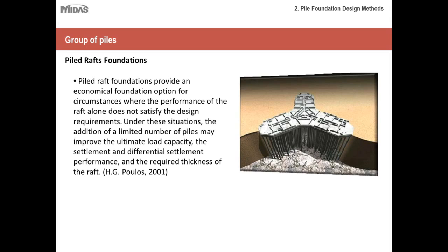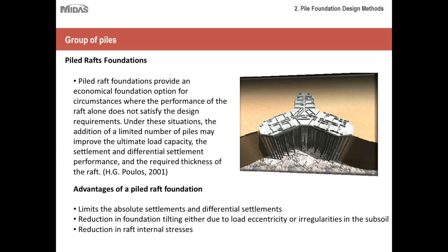So this definition was coined almost a decade ago. And after that came the high-rise buildings, where the superstructure and substructure interaction became so important that the raft became an integral part of the superstructure, and therefore we no longer limited ourselves to this limited number of piles definition. Now you can add hundreds of piles under a raft. And let's see what the advantages of piled raft foundations are in that case.